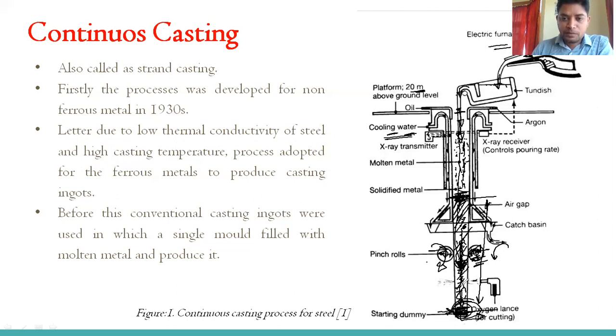Once this material comes out, this portion will reach the bottom. As we have already kept this dummy block closed in the beginning, whatever material reaches this dummy block when this section comes out is automatically completely solidified. Because of the compressive force applied by this rolling, there will be a continuous movement of the solidified part.